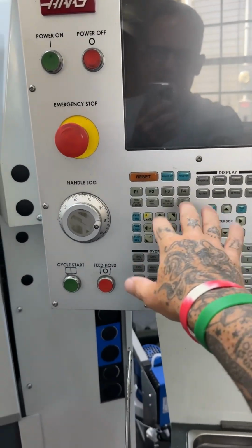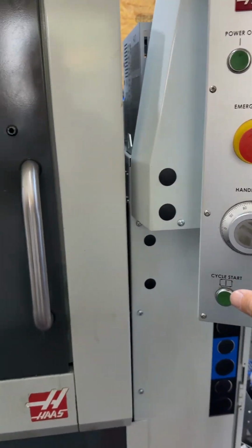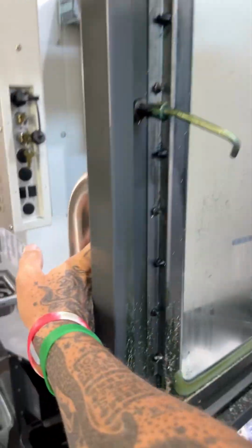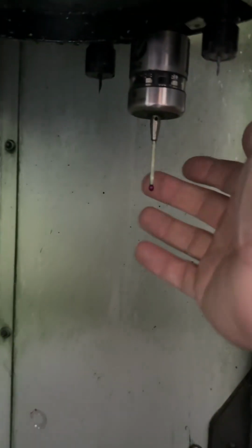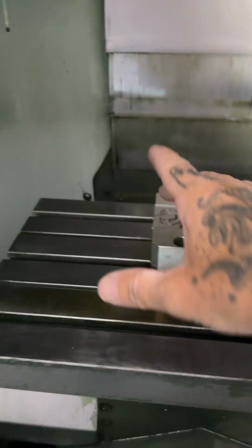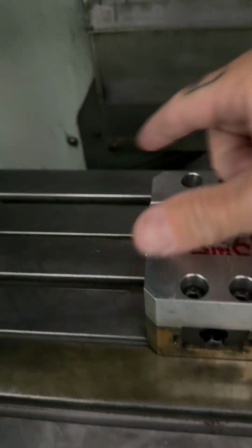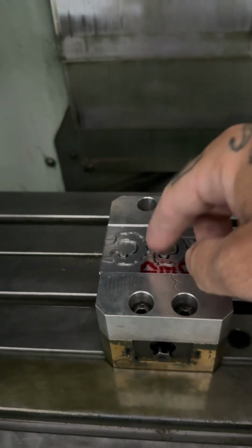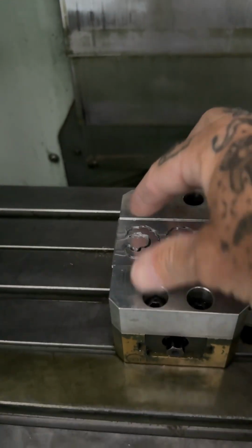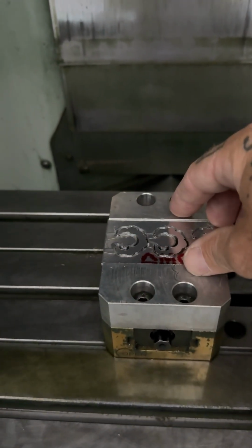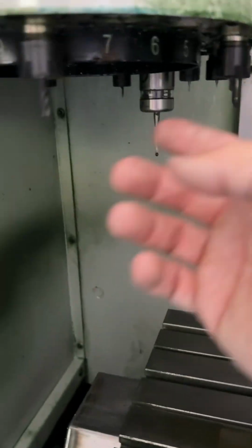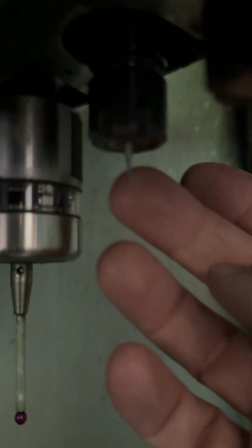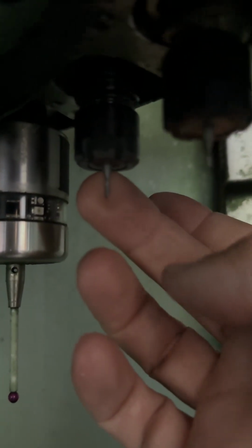I would just then adjust and find a certain point using the probe, which is this tool right here. The probe would touch off the area, boom, boom, and then the top. So I get my X, my Y, my Z. It would know then where that item is in relationship to this piece of stock, and it would start milling it. So my 1/16 end mill is right back here, which you can see is very small and very delicate.